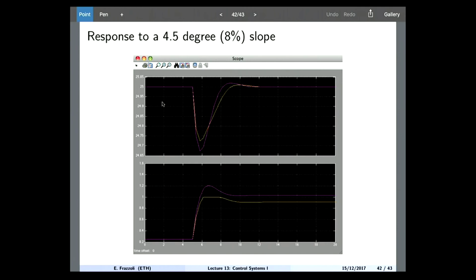So, word to the wise, every time you are designing a control system with an integrator in a real-world setting, make sure that you also add this anti-wind-up scheme. Make sure that your integrator doesn't just go to crazy values just because your input is saturating.